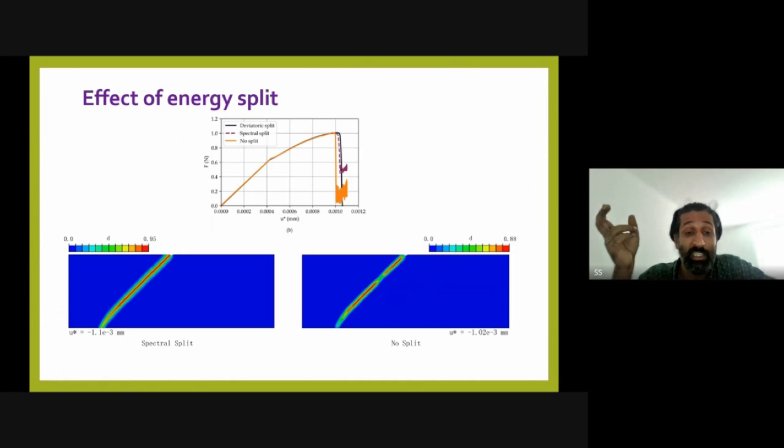Interestingly, in this part we do get phase field patterns which are along the shear bands, but usually we do not get the evolution that is complete. We suspect that is because we are using the damage activation surface, and since the driving is different, there is a considerable amount of stress redistribution happening here, which makes the phase field evolution not imminent.